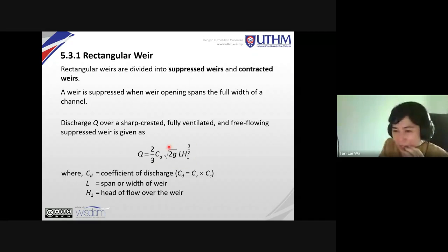Now, where does this formula come from? Typically, whenever you see a rectangular weir, this is the formula. It comes from experiment. I believe you have gone through the Buckingham Pi theorem to create formulas. That means you know that you have the parameters Q, C, L, and H, and you arrange them to get this formula. Now, as I told you, CD could be given, or the question could give you CV and CC.